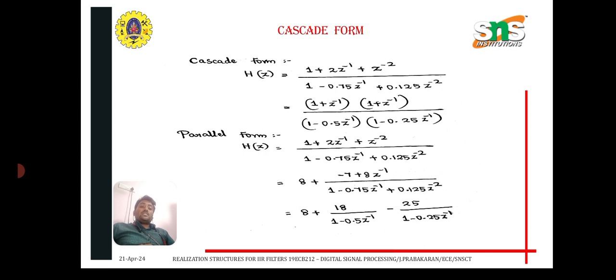Apply partial fraction. By using partial fraction we can get individual H1 of z and H2 of z. That is, H of z equal to H1 of z plus H2 of z. Apply direct form to both H1 of z and H2 of z, and finally we connect each transfer function in series manner. We will get the cascade form realization.